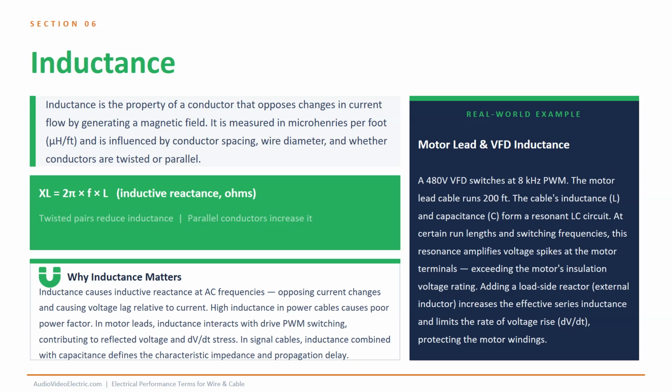In VFD motor leads, cable inductance interacts with drive switching, sometimes amplifying voltage spikes. Adding a load-side reactor can increase inductance and protect motor windings from excessive voltage rise.